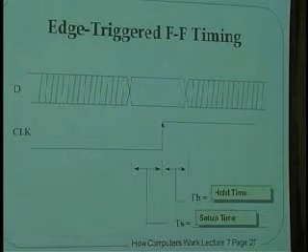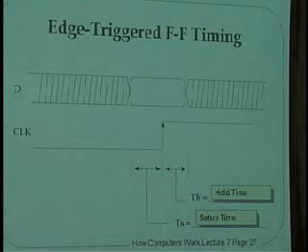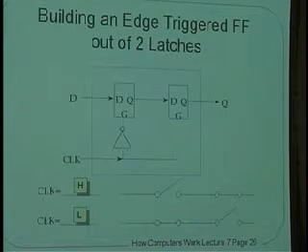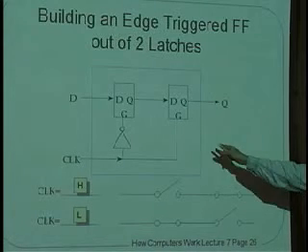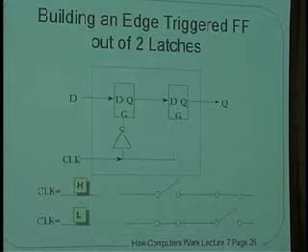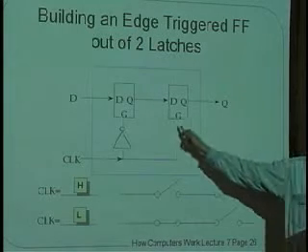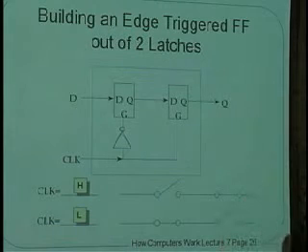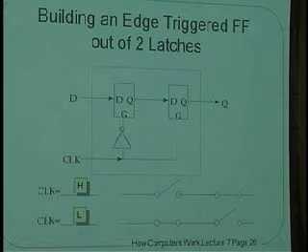Yeah? Does the fact that it in one case has to flow through a NOT gate and the other case doesn't present a timing problem? Yeah, it turns out that you have to be a little careful about the overlap of the two G's here, okay? And in general, you want the signal on the second one to happen a little bit sooner compared to the first one. And if you want to, you can work that out. That doesn't matter right now.